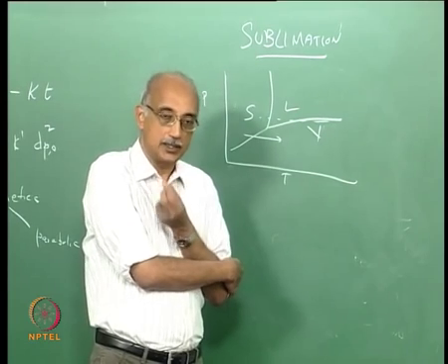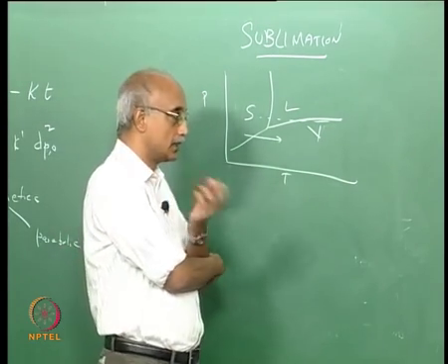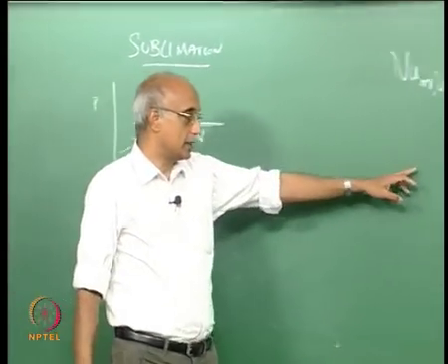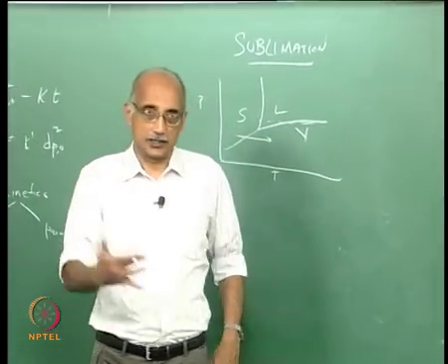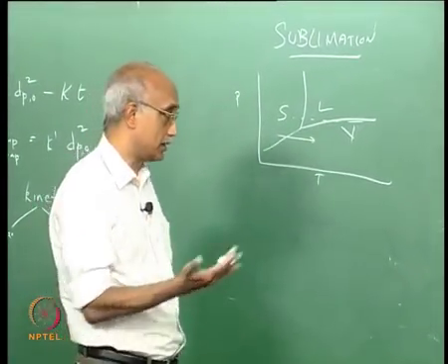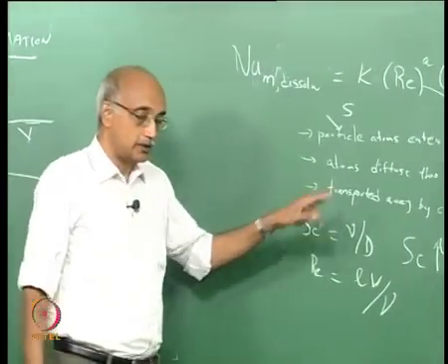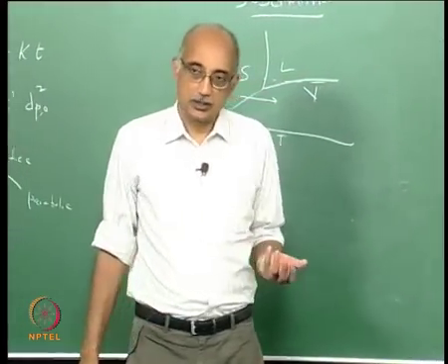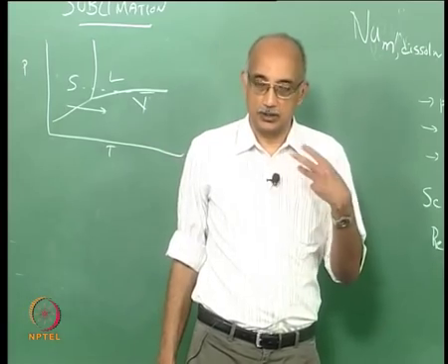So, there should be a tendency for spontaneous evaporation of the material from its solid form, and then just like you have a liquid boundary layer surrounding the particle in the case of dissolution, you will have a gaseous boundary layer surrounding the particle in the case of sublimation. And just like you can promote dissolution by introducing convection, you can also promote sublimation by introducing a convective process.